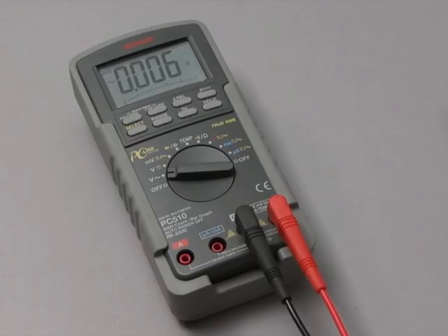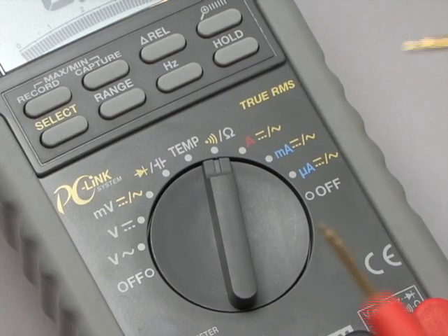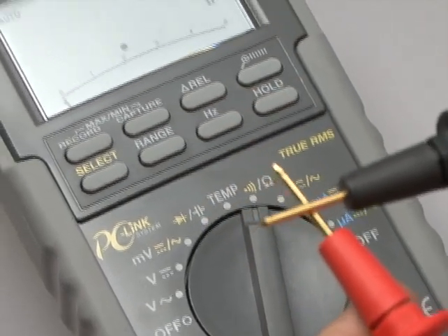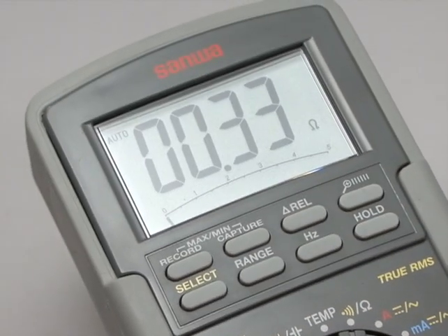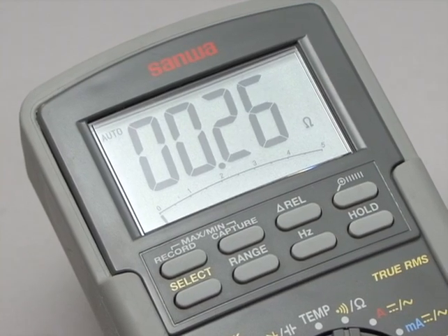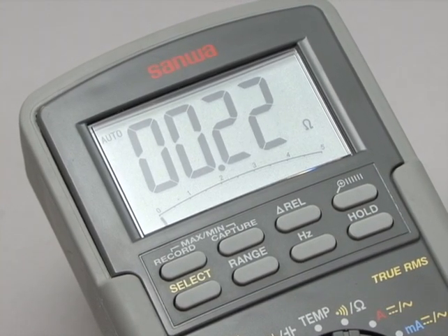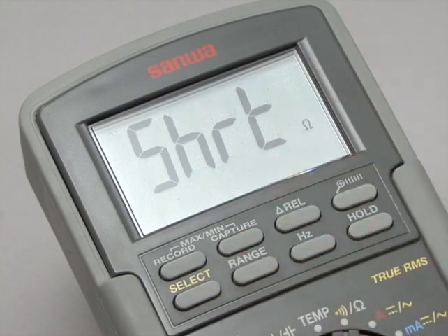The precautions adopted with the analog tester should also be adopted when using a digital tester. For example, the practice of making 0 level adjustments should be followed before starting measurements. Refer to the instruction manual, because methods for making zero-level adjustments vary according to the type of tester.